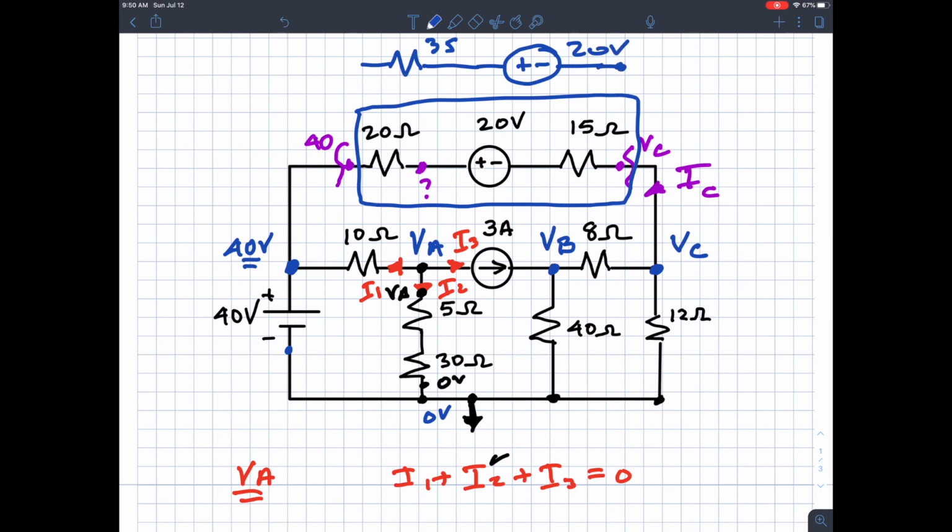And we've talked about equivalent resistance before. If I replace the things that are in the box with this circuit right here, then with respect to the node voltages, these circuits would perform exactly the same. And if I do that, I'm able to write node voltage equations. So that's the thing that you have to do. Typically, I don't redraw the circuit. I just notice the equivalent circuit and mentally make an equivalent circuit in my head and move forward to write the node voltage equations. But I'm not going to do it that way.